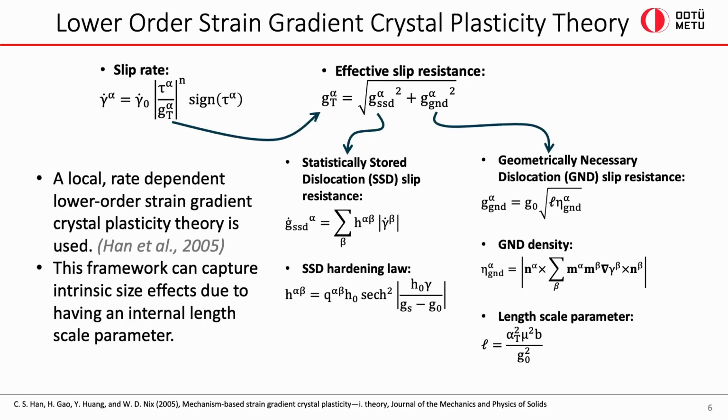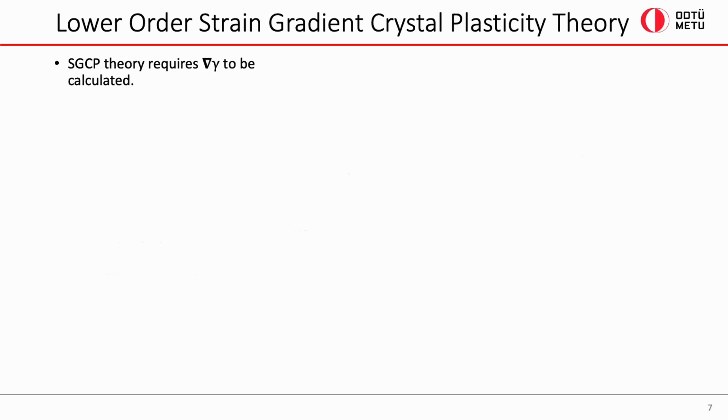So the issue with this framework is that the equations are simple, but the gradient of plastic slip must be calculated. And in finite element method, since plastic slip is not a degree of freedom in this model, calculating the plastic slip gradient requires additional finite element operations.